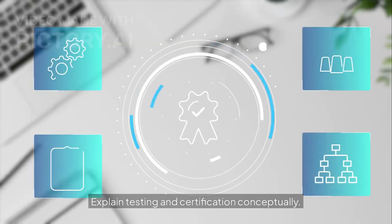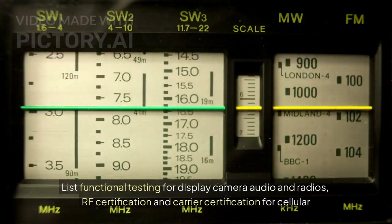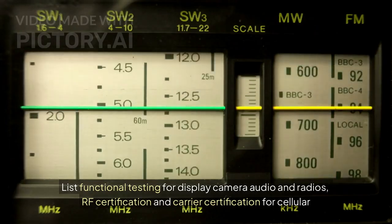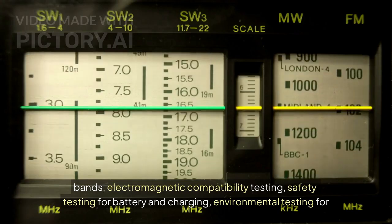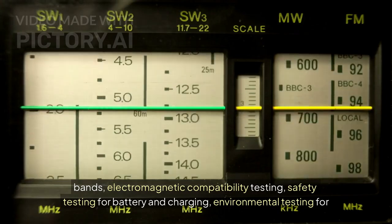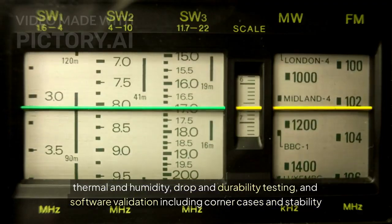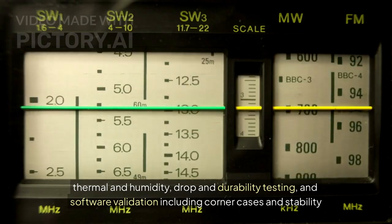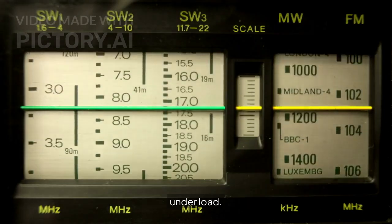Explain testing and certification conceptually. List functional testing for display, camera, audio and radios, RF certification and carrier certification for cellular bands, electromagnetic compatibility testing, safety testing for battery and charging, environmental testing for thermal and humidity, drop and durability testing, and software validation including corner cases and stability under load.